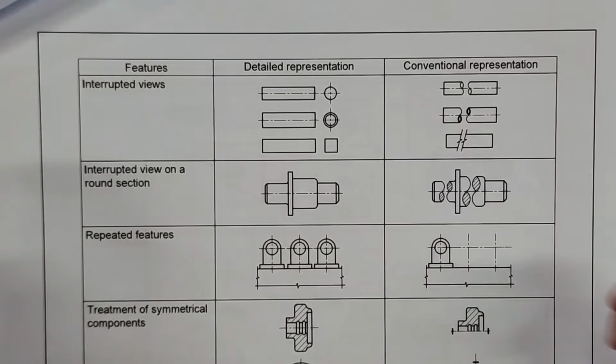All right, we're almost finished off with this part before we get to the machining. Just that I'm mentioning here, that's important. So CSK stands for countersunk. That's something that's been asked in the past. Just take note again how these measurements are, especially the diameter signs. A lot of times the kids forget the diameters. The counterbore, the abbreviation there is C bore.